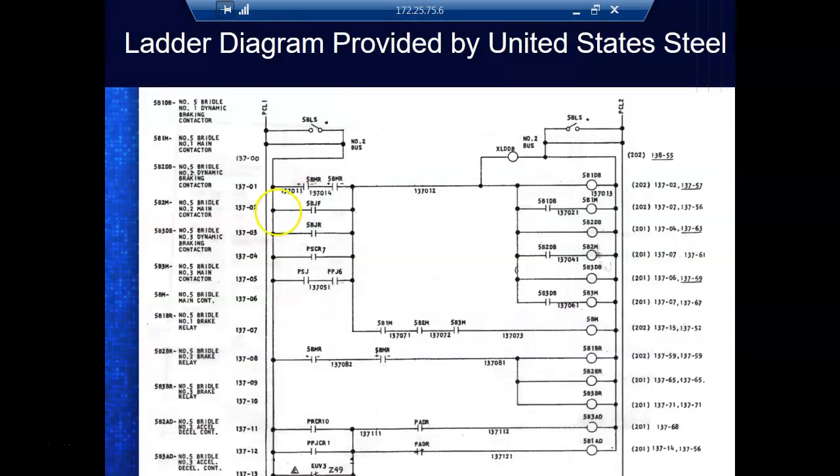So what we see here, if y'all can see my cursor, is that this line is line 1 on page 37. The 37 just says that this is the 37th page. This is line 1. Okay. But this is a rung, but it's got multiple lines. This is line 2. But we got another line that lines up horizontally with it. It does not have a line number, so it's the same as line 2. So any line that lines up horizontally gets the same number.